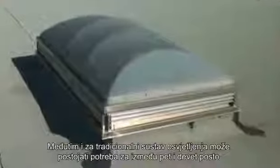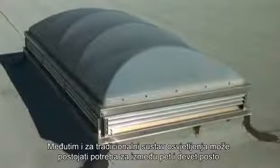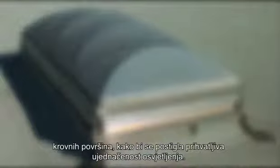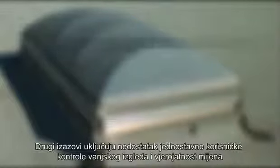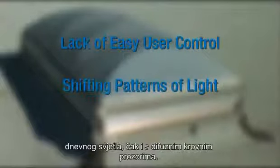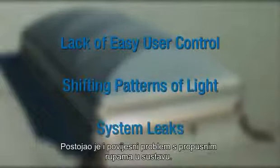However, a traditional top lighting system may need between 5 to 9% of the roof area to achieve acceptable illuminance uniformity. Other challenges include the lack of easy user control of the output and the likelihood for shifting patterns of light, even with diffusing skylights. There has also been a historical problem with system leaks.